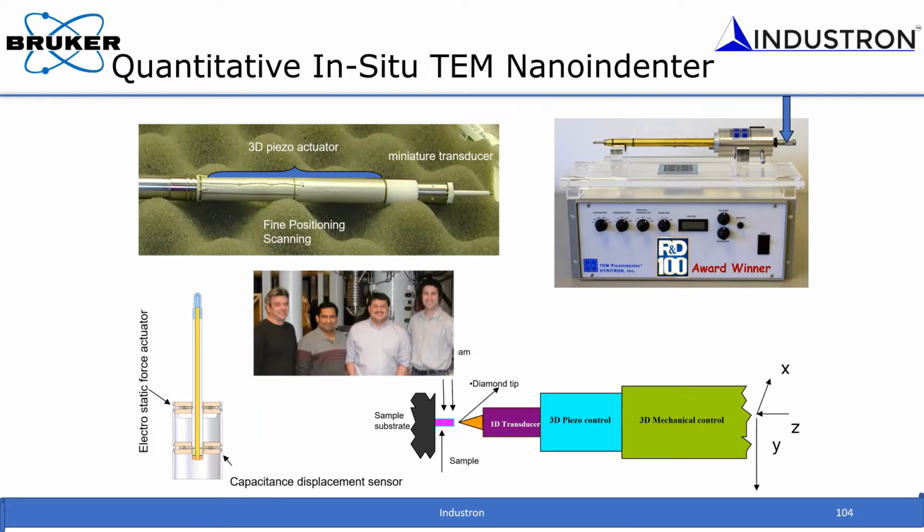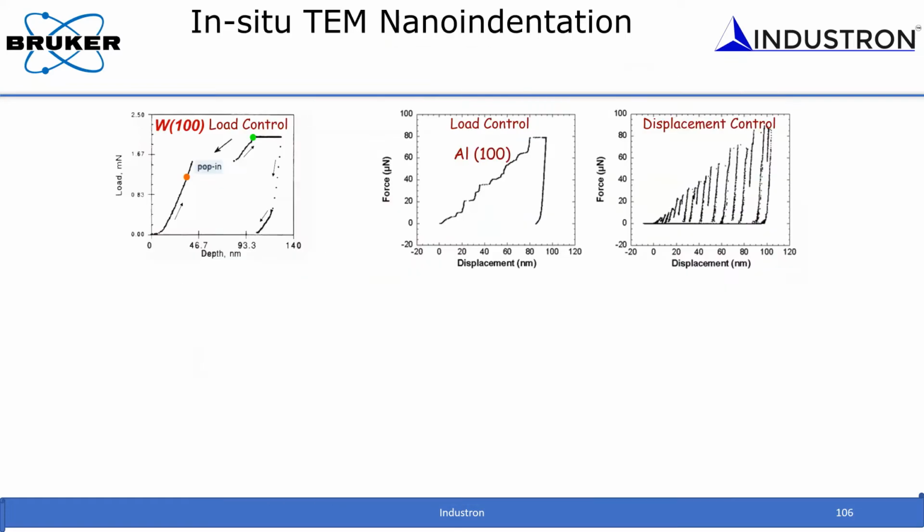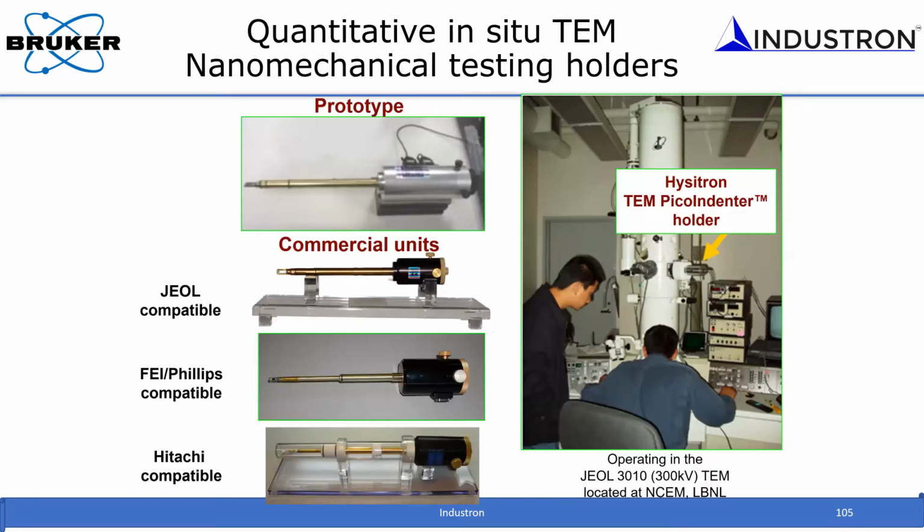The very first experiment, as you would expect, was to understand what happens when you bring two materials closer together. If you have a system where the dislocation density is low, and the stresses can reach the theoretical stress, can you see dislocation nucleation? This is the first thing that I wanted to do, so that is what we did in the very first few experiments inside the TEM.